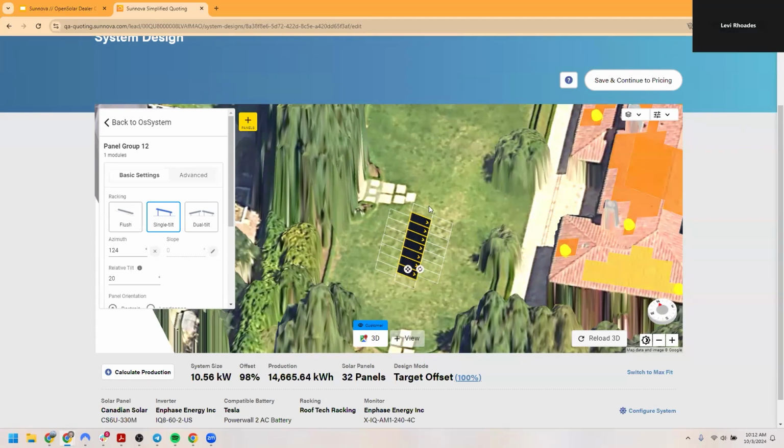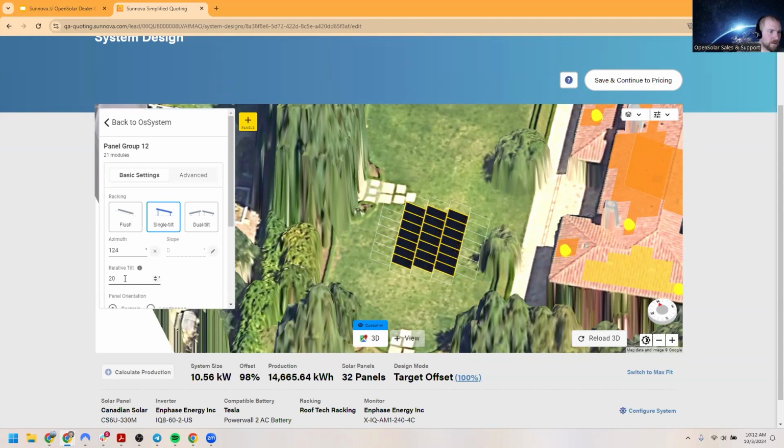So dropping some panels onto what we see as more or less a flat surface with no slope, I do get an automatic sort of tilt-up rack there. And what happens when you start adding panels into a preset tilt rack like that, you're going to have each next row on its own 20-degree or whatever input tilt you have there.